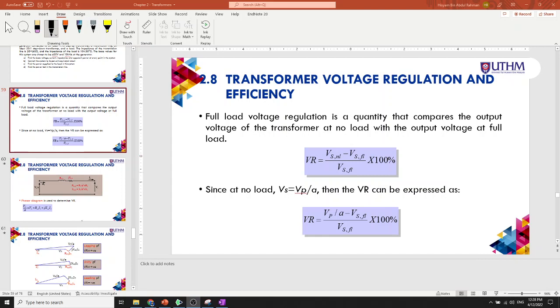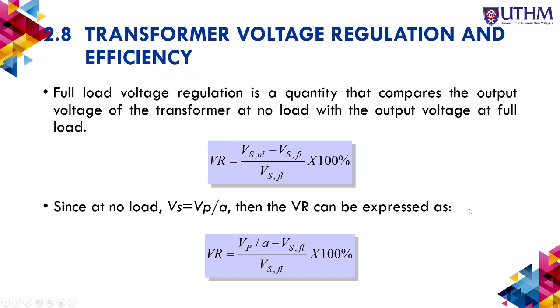Okay, let's continue. Just now we finished determining the component values. Now we want to measure the voltage regulation and also the efficiency of the transformer.